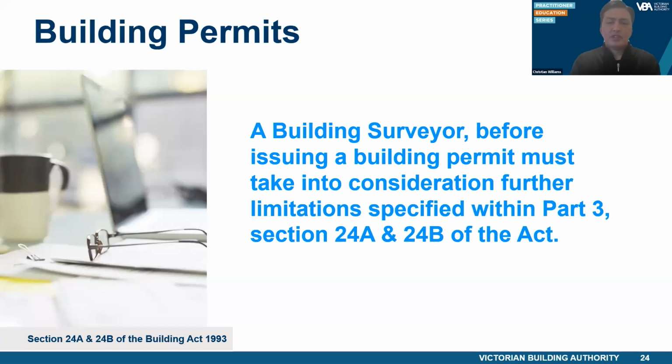For the purposes of Section 24B of the Act, where the cost of the building work does not exceed $10,000, anyone can carry out the building work, as there are no registration requirements where the work is less than this amount. Where the building work is domestic building work more than $10,000 carried out under a major domestic building contract, the builder must be the builder who entered into the contract and whose registration authorises them to carry out the work.